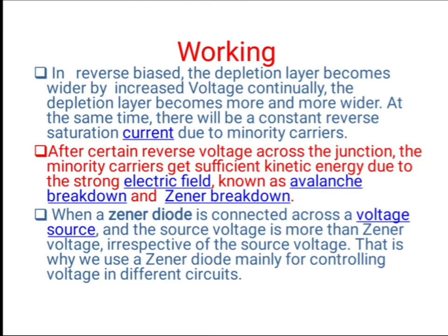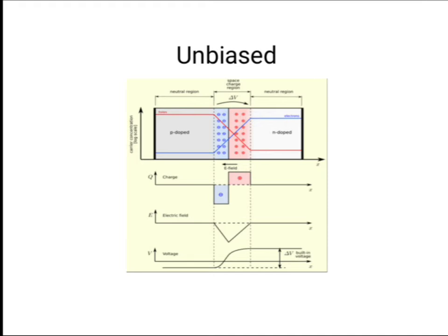In avalanche breakdown, electrons get multiplied. The agitation of those electrons makes them vibrate and hit others, the others go and hit more, and likewise it goes on multiplying. This kind of breakdown is called avalanche breakdown. Whereas in Zener breakdown, because of the applied voltage across it, the Zener voltage makes the electrons move. This is taken as Zener breakdown.